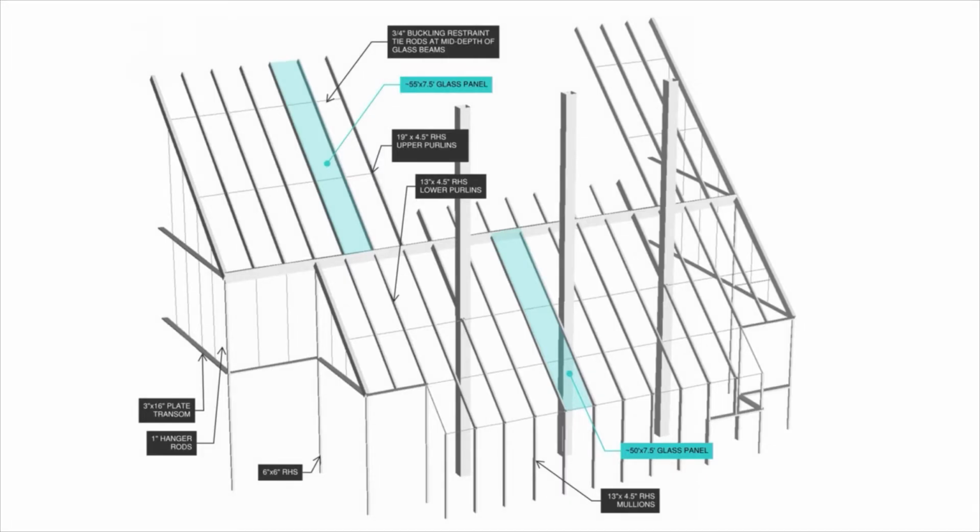So we established a hierarchical steel structure where we had a primary steel girder that split the structure in half. Again, it's a very large structure, so we found that we couldn't do it without any steel. We couldn't do it only in glass. And then we had this unidirectional steel framing to really open up transparency when you're walking out of the building or walking into the building, looking through the vestibule itself.